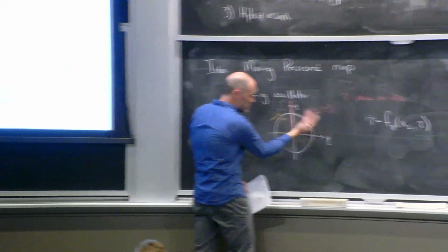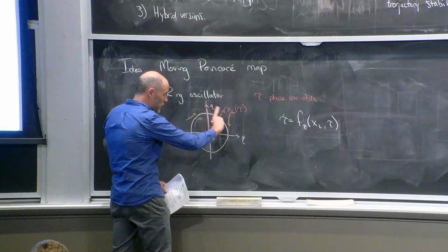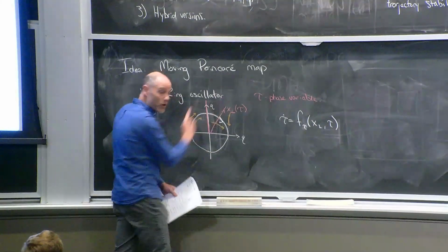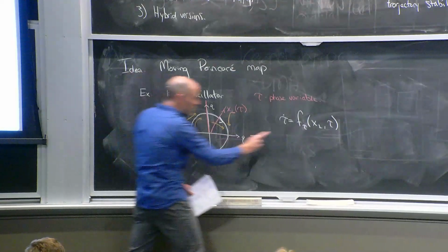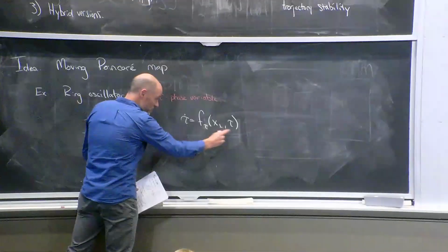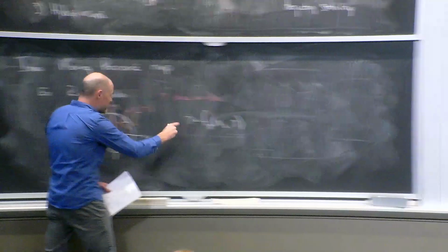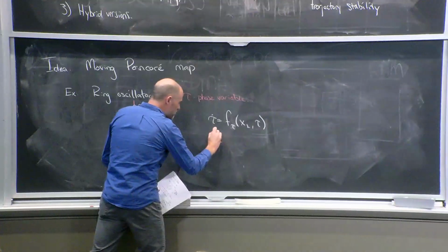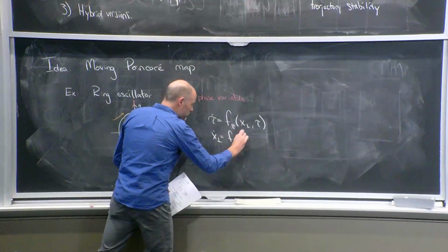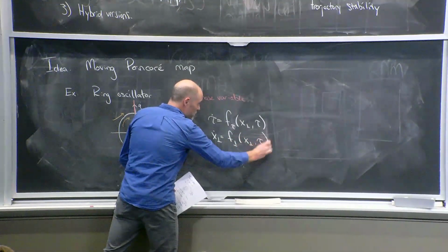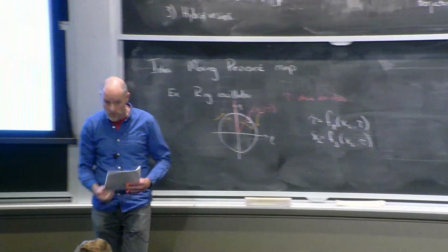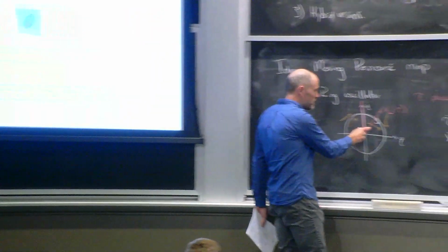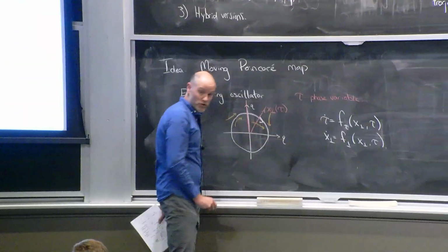I can completely tell you what state I'm in by just knowing which section I'm in, which tau I'm in, and what my coordinate is in that tau. And as a function of those things, that complete representation of the state, I can tell you how time is evolving, and how x perpendicular is evolving. It's just a different coordinate system to write my dynamics in. And again, for the simple ring oscillator, it's just like polar coordinates.